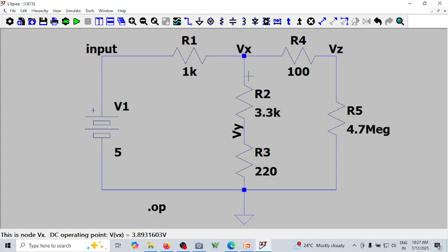So this is how, using the netlist, you can label any net of your interest. It's not required in all cases. If you want to know the voltage at a particular point during analysis, instead of searching for the node number, you can label that node or net, and then see that voltage exclusively there.